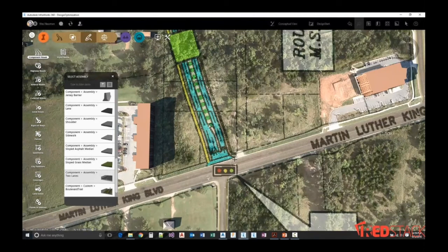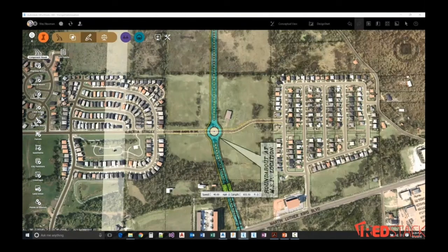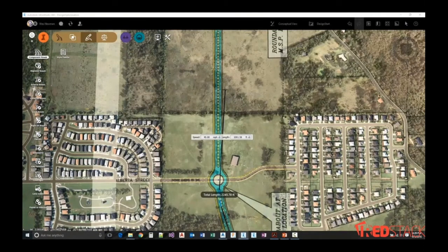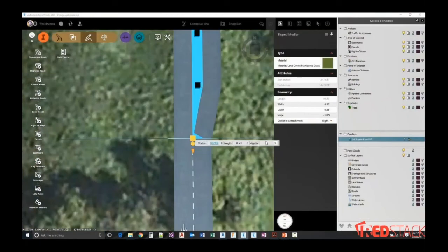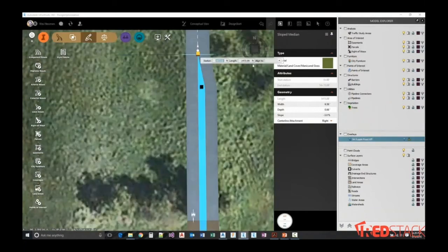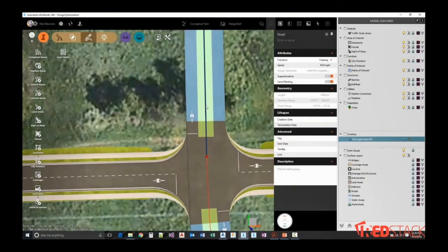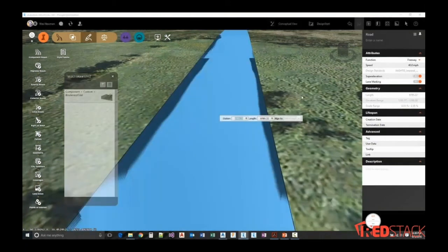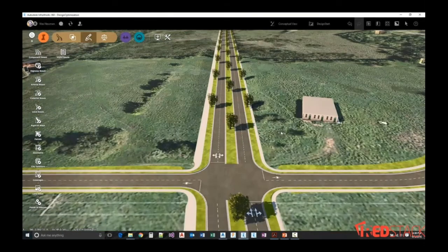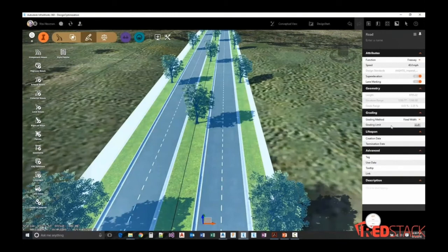What we're doing is laying out a road section and using design rules and real engineering capabilities. So this is a conceptual application with easy-to-use tools to put together a design proposal, just based on a 2D PDF. We can very quickly apply multiple cross sections and see what the impact is, looking at earthworks very early on in the design phase. The tools make it easy to change intersections, like here where we're putting a roundabout in place of a traditional intersection.